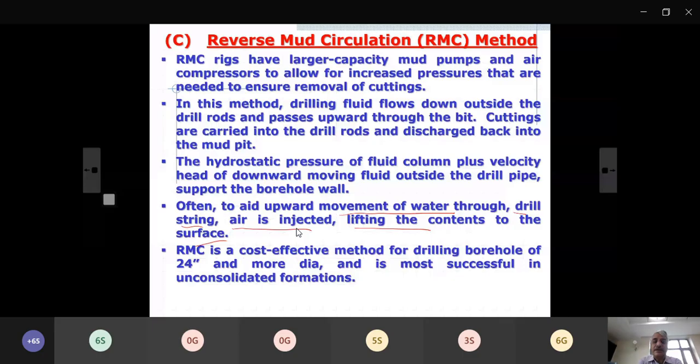And as I told you, it is normally required or used for bigger dia piles. So normally in railway our diameter of pile is 1 to 1.5 meter. 1 and 1.2 meter are most common. Some cases we go 1.5. These are two standard, 1 meter, 1.2 and 1.5. They are most commonly used dia.